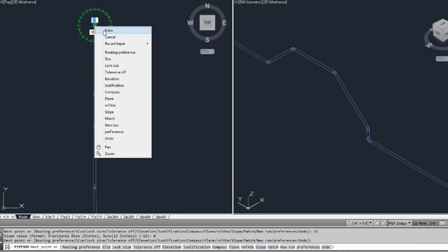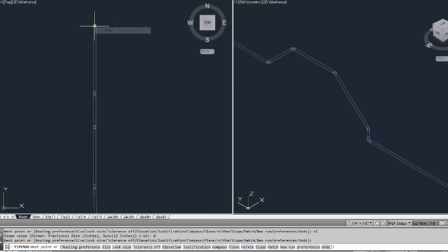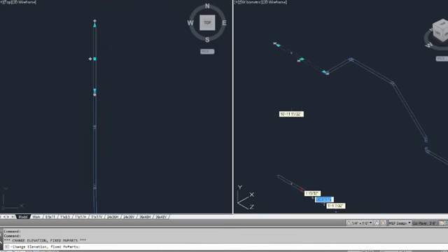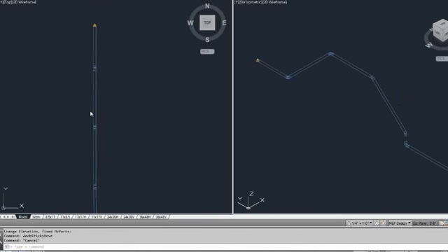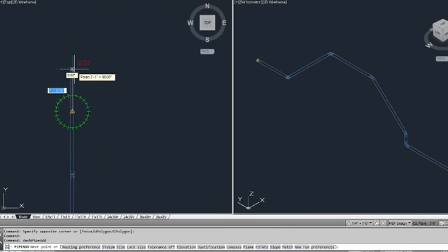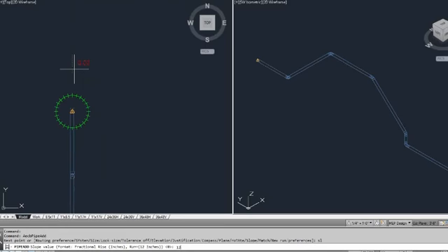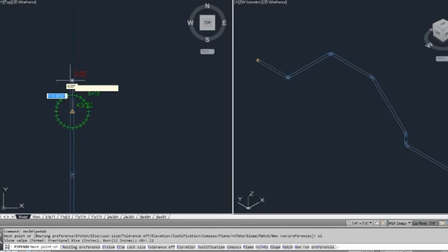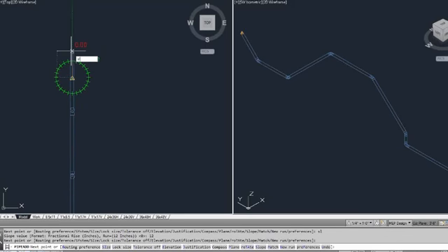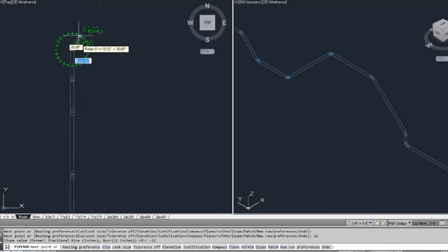And what I did is that now I put in another offset that is very similar to the first, except I'm using a rolling offset. So let me try that one more time without getting that 90 in there. So slope of 12, I'll put a short little piece of pipe in, slope of 0, another short little piece of pipe, and then a slope of -12, and another short little piece of pipe, and then I'll continue on.